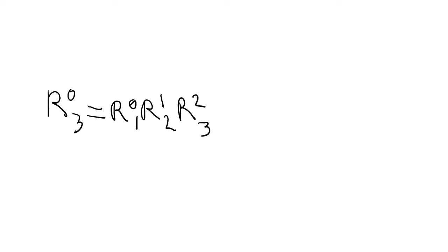We've now learned about both rotation matrices and displacement vectors. We've learned that we can make a complete rotation matrix all the way from the base frame to the end effector frame by multiplying together each of the individual rotation matrices from one frame to the frame next to it. But we also learned that we cannot do this with displacement vectors.